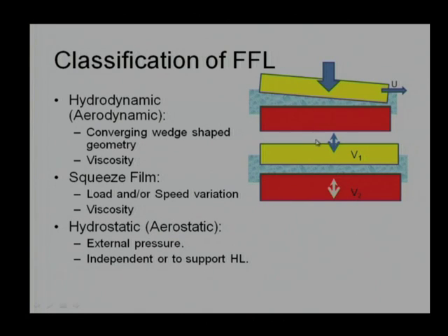Or if there is a load applied which is initially maybe say 100 Newton, reduces to 80 Newton. Naturally, when load decreases, this block will move up. If loading increases, this block will come down, or say reduce the film thickness. So, indirectly even the load is going to induce the velocity of the yellow block. So, whichever the situation is, squeeze film action will occur if there is a relative movement of the yellow block with respect to the red block in the direction of film thickness.